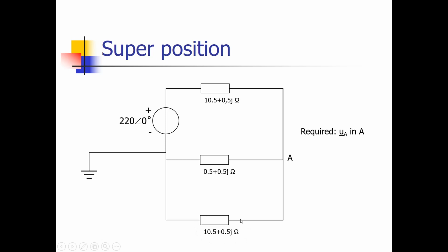So when we have this, we can do the second step, which makes life much easier because we see here two impedances in parallel. So we can replace these two impedances by one impedance, and we can do that in the following way. We can say, well, 1 over the replacement impedance is 1 over this impedance plus 1 over that impedance.